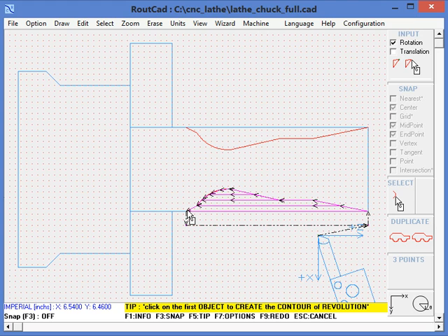The requirement was that we needed to have half an inch of clearance. So each time it finished a pass, it also always retracted half an inch away from the material and then went back in. And also the depth of cut per pass roughing was set to half an inch.